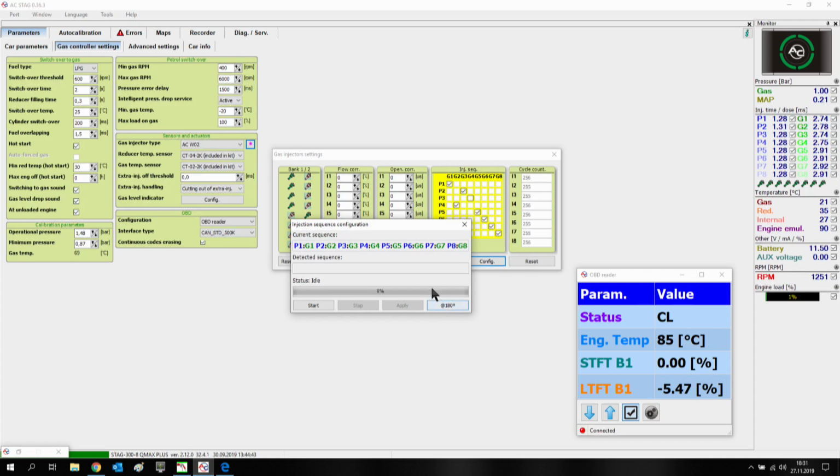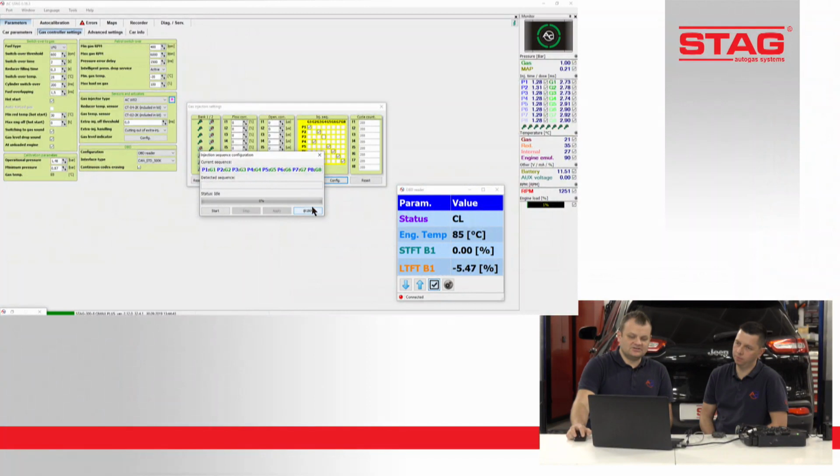This function is useful for 4-cylinder, 3-cylinder engines with the problem of small jerks when going from cutoff to fuel on, especially in Hyundai and some Toyota engines, when after cutoff you press the throttle and feel 2-3 jerks sometimes.